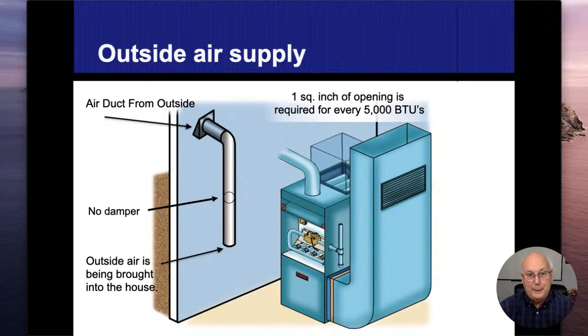That's completely acceptable. If I have a crawl space that's part of the exterior of the house, so it's in the unconditioned space, we're not heating it, we're not cooling it, we're not insulating it, I can bring combustion air from there as well. Typically, they're going to go through a sidewall, and they're going to bring everything from there.